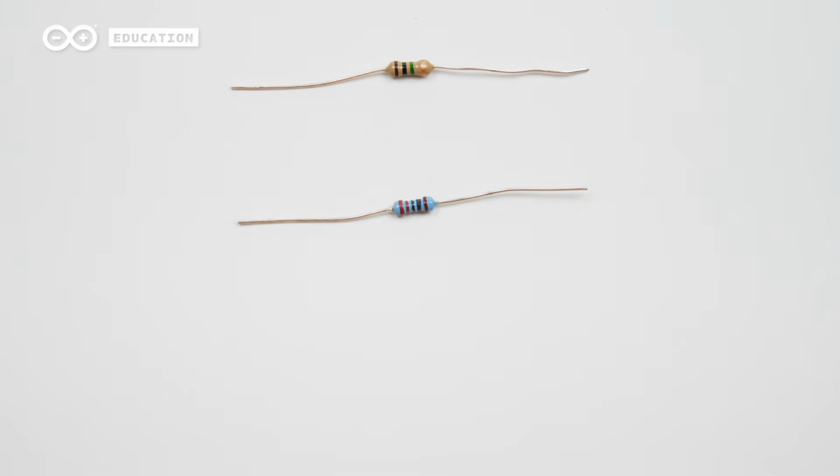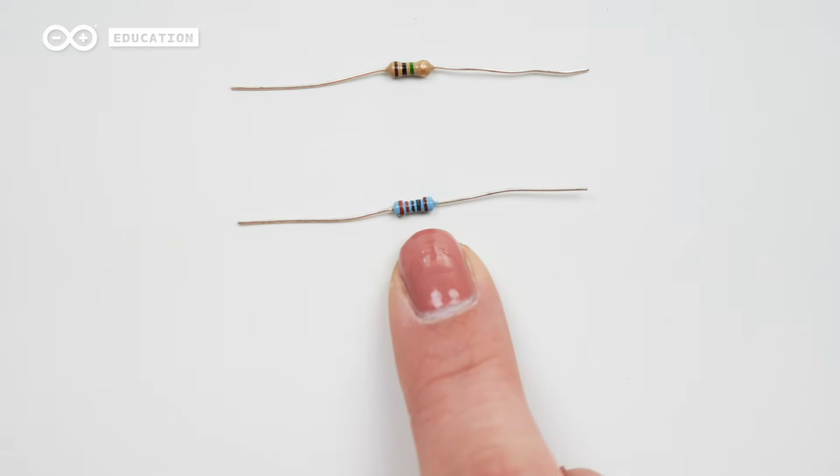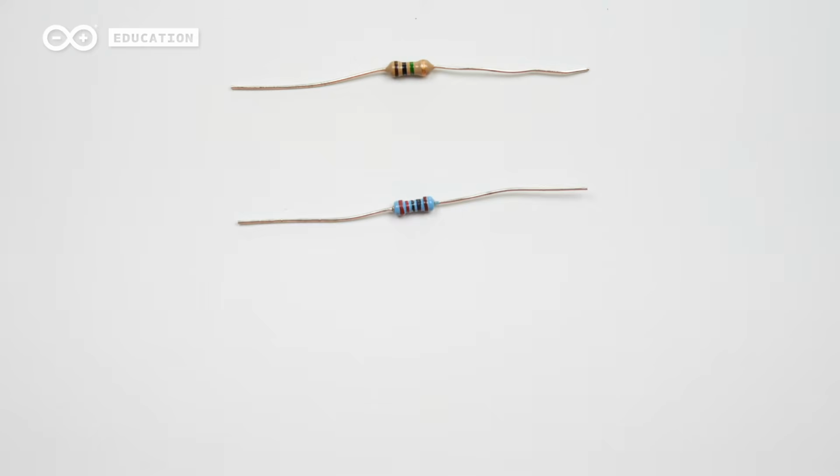Identify the color of the band and match it with its corresponding digits in the table from page 41. First one is red, so that means number 2. The second one is also red, and that means number 2. The third one is number 0 because it's black. And same for the fourth one. It's black, so it's number 0. Since the fourth band is a multiplier, it means that this is a 220 ohm resistor.